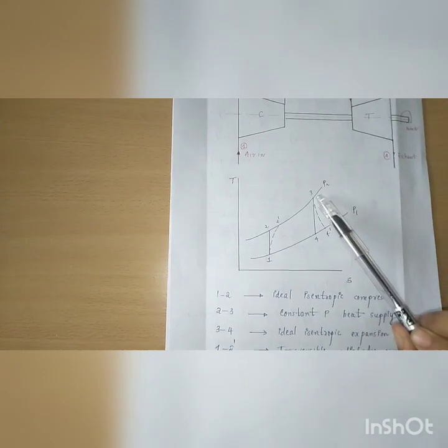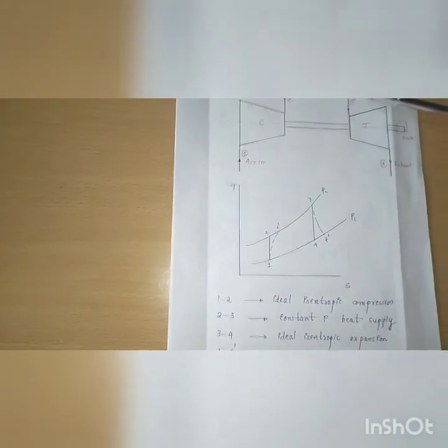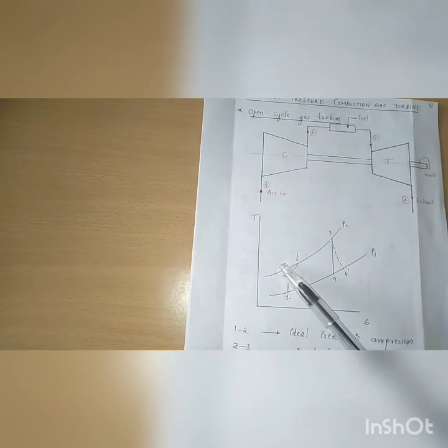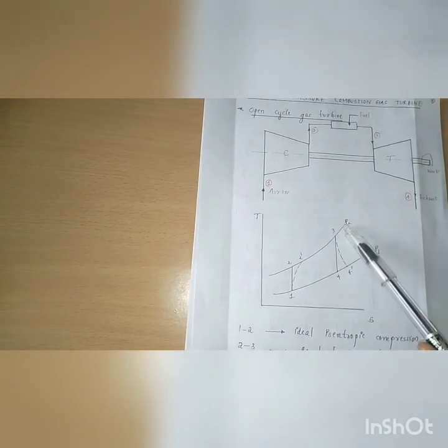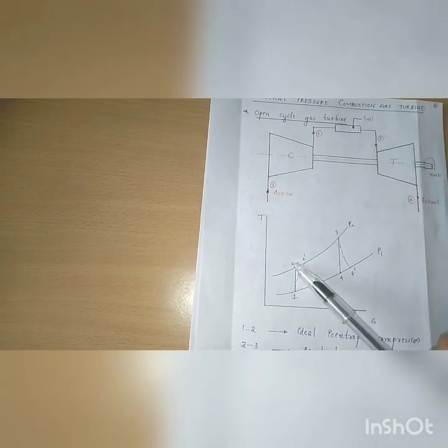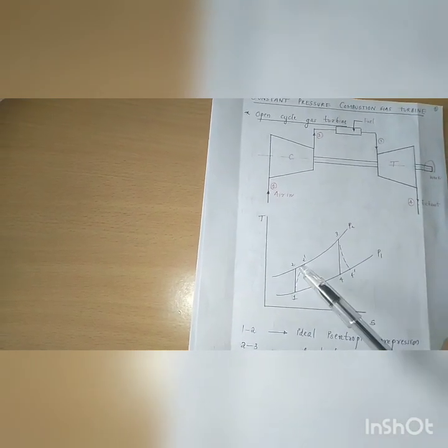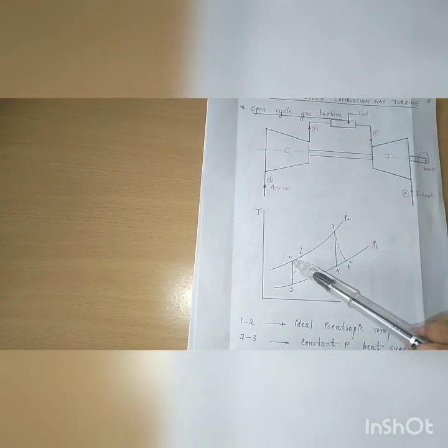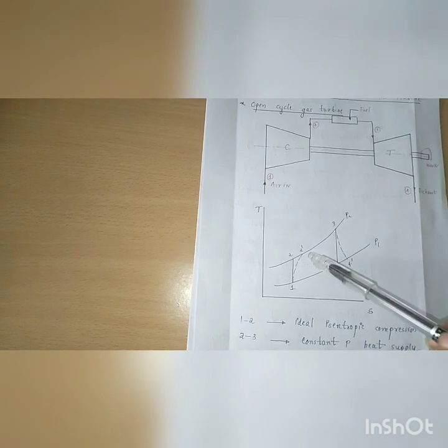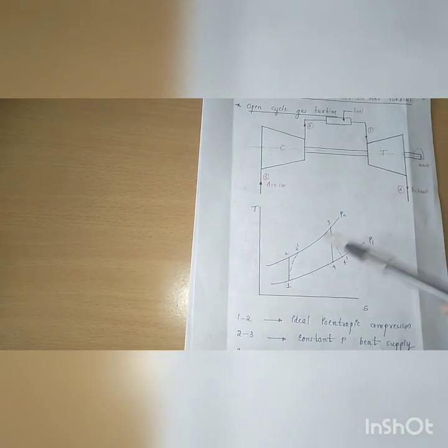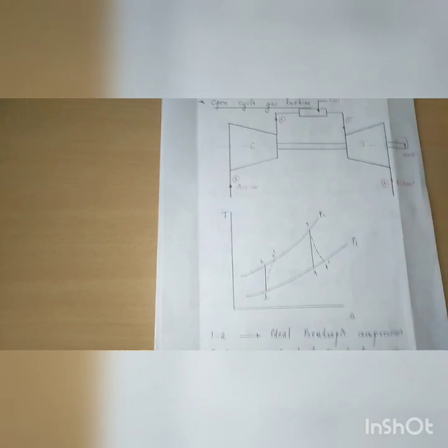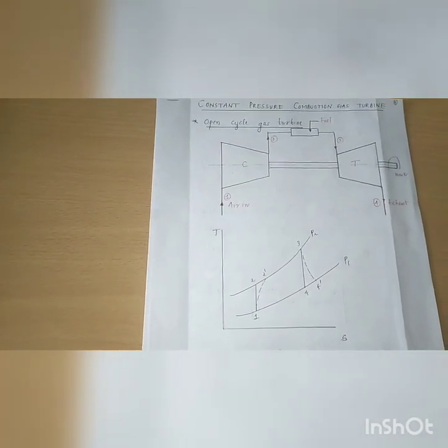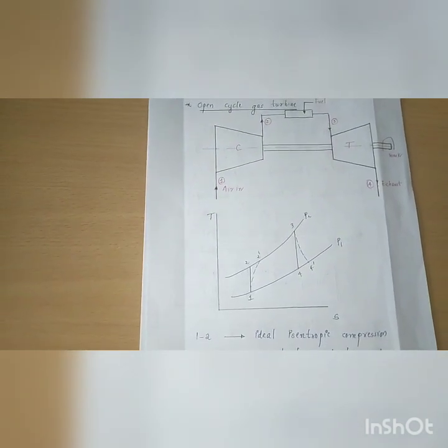Then again 2 to 3, we are adding the fuel. That is the combustion process. The combustion process takes place at constant pressure P2 and the temperature is increasing from T2 to T3 or T2 dash to T3. In the ideal case the temperature increases from T2 to T3, and in the actual case T2 dash to T3. Then after the combustion process, the hot gas is expanding in the turbine, that is T3 to